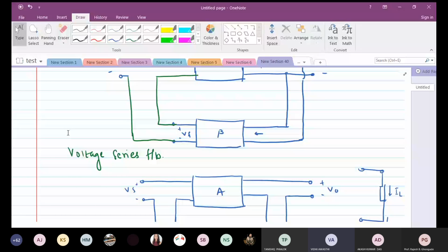Before starting this, sir, I asked you a question: if we change the values of beta or other factors, then other things will change, so for this reason only we use negative feedback. Exactly. That is what we are trying to say for such a long time, that we want to make the overall voltage gain independent of the device parameters. Device parameters can be specifically the HFE. I'm not referring to beta because this beta, that beta will cause confusion. That is the reason why I'm using HFE.